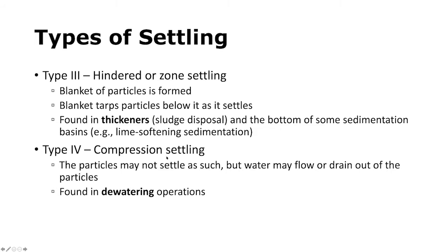Type 4 settling is compression settling. In this mechanism, the particles may not settle as much, but the water may flow or drain out of that thickened blanket of particles. This is what we really see with dewatering operations for solids handling.